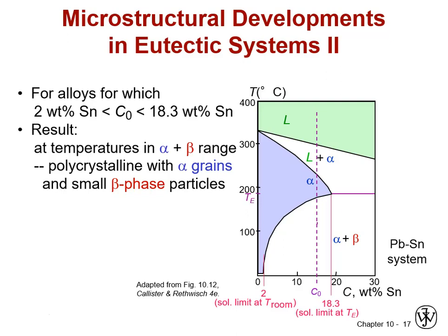temperature. And down to room temperature is important in this case because that's where things stop diffusing, and in some cases, even if you crossed a phase boundary, around room temperature, metals don't diffuse fast enough that things would change. So even if you crossed a boundary into another equilibrium regime, you might not actually see that phase transformation just because it's too slow.